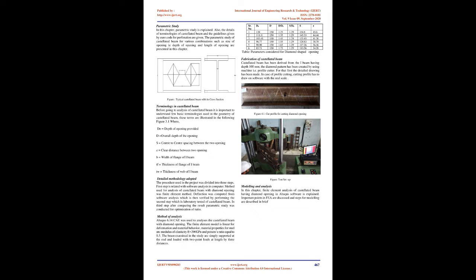Castellated beams are the beams having different geometrical shape perforations in the web of beam. Different shapes such as hexagonal, circular, rectangular, diamond, sinusoidal etc. are used in castellated beams. These shapes are constructed with the help of computer-controlled cutting torch to cut the section according to given geometry. Types of castellated beam. Depending upon opening there are different types of castellated beams. Following are the different types of castellated beams: circular opening, sinusoidal opening, diamond opening. Figure: castellated beam with diamond opening.